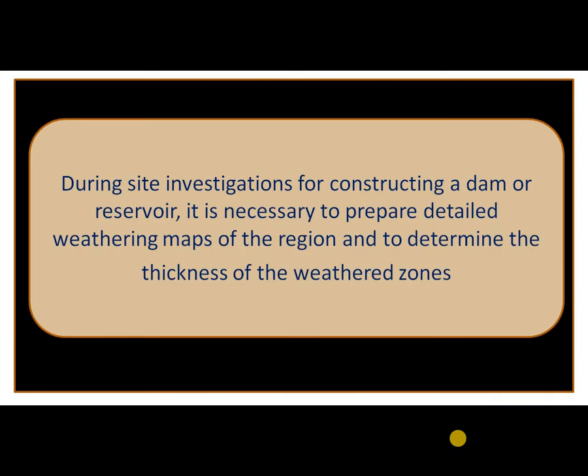During the site investigations for constructing a dam or reservoir, a civil engineer must necessarily prepare detailed weathering maps of the region and determine the thickness of the weathered zone. These are the two important points which are to be remembered. One is preparation of weathering maps and the other one is to determine the thickness of the weathered zone in the site where a dam or reservoir is proposed.